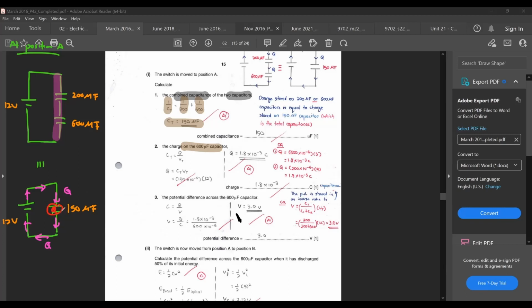The charge that is released is actually from one plate of your capacitor. It will flow through your circuit and then go to the other plate. This one was what I mentioned to you. This is the charge that is seemingly stored by your capacitor. They separated the charges, so there is positive and negative on one side. But then when you want to discharge it, the charge on one end is released so that it can flow back to the other end. Okay, this was the charge that people always think to be seemingly stored by your capacitor.